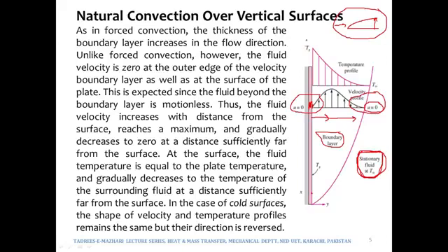And let's take a look at the temperature profile as well. Over here you can see that Ts is greater than T infinity. So in fact this is the case where the fluid will get heated up. When we are closer to the surface, the temperature of the fluid would be closer to Ts, would be higher. And when we move away from the surface, the temperature will eventually come closer to the value of T infinity.